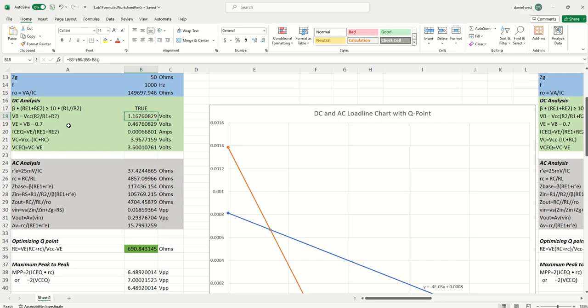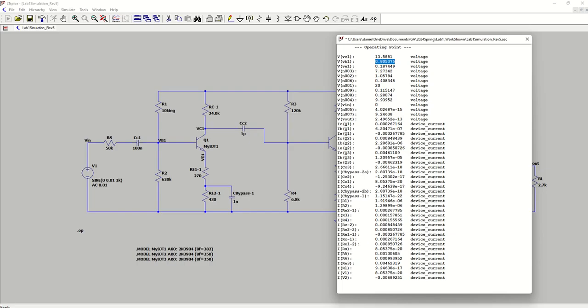And if we have a lower voltage through the emitter, then using Ohm's law, the voltage through the emitter divided by the resistance of the emitter, for me it's RE1 and RE2 because I'm using the swamping resistor, then the current's going to be even lower. So my current, I'm using 668 microamps, and I go back and look at this, and I go down to the emitter for the Q1, and I'm getting 267 microamps, which is significantly lower.